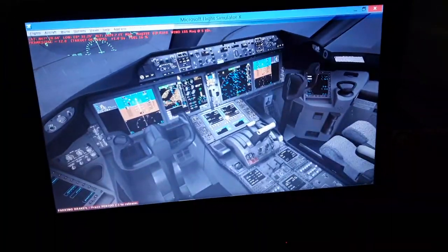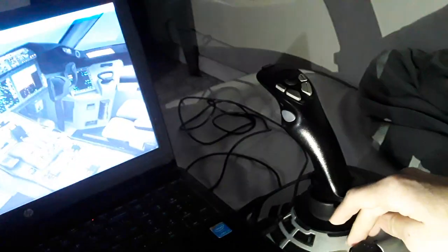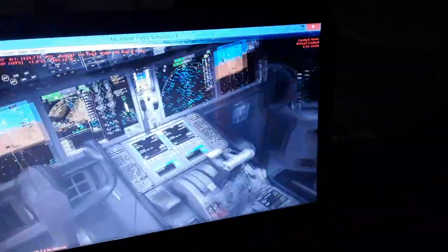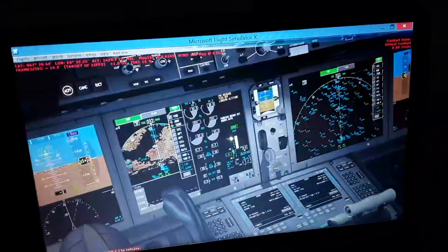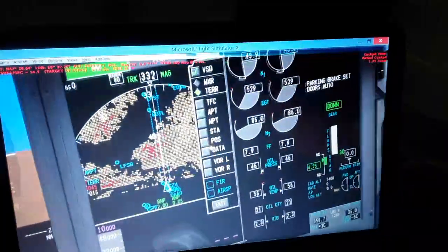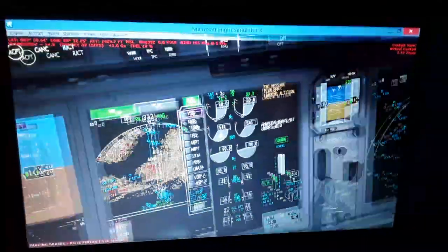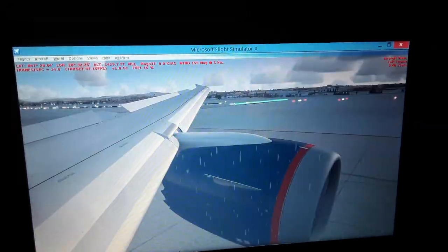And we have also the rudder pedals over here. We have the thrust levers over here. We can control using this slider over here. So this is the thrust levers. You can see the thrust indication commanded by the FADEC. The FADEC over here displays all the engine data, so I'll explain it to you in a couple of minutes. Also the outside view of the aircraft, the aerodynamics.